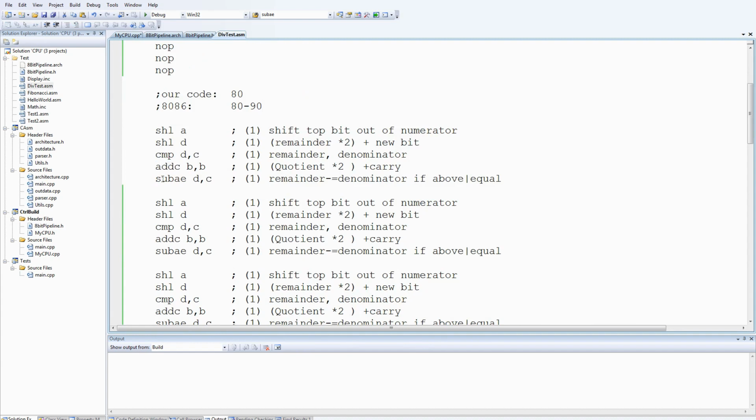This add with carry will overwrite the arithmetic carry flag when it's in pipeline stage 2, so that would take effect when this instruction is in pipeline stage 2. So whatever we're going to do to implement this instruction's difference between subtracting and not subtracting needs to happen in pipeline stage 1 before the carry flag is overwritten.